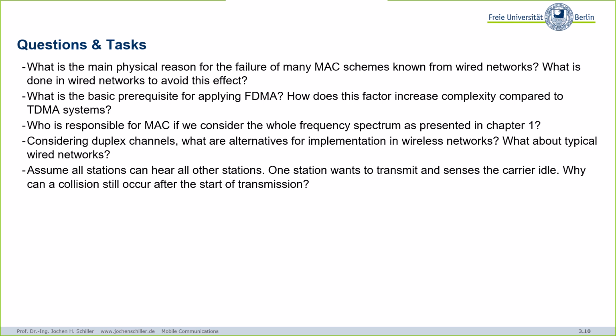Exactly. Another answer is different antennas for different frequencies. So yes and no, it depends on the frequency range. For example, you can use a 900 megahertz antenna also for 1800, also for 1900. Maybe it's not as good, but it works. 900 and 1800. Why? Because this is just twice.